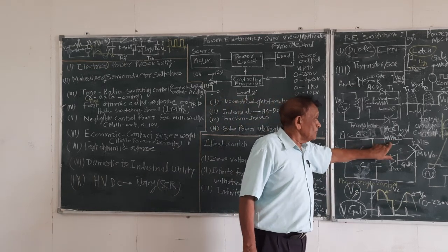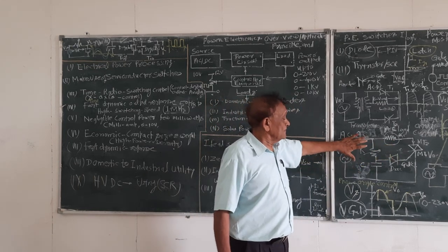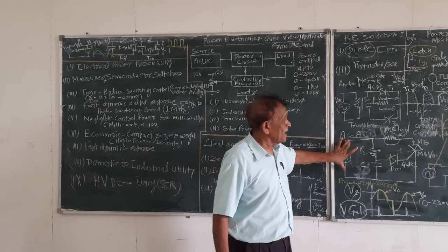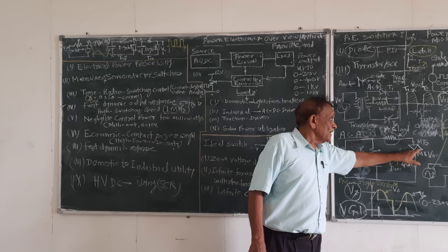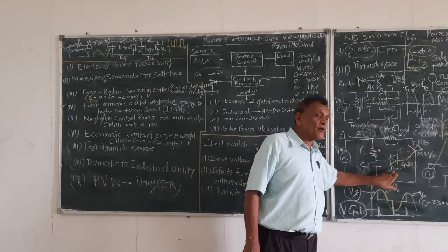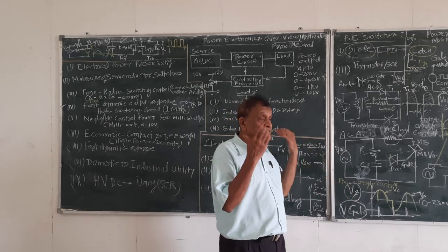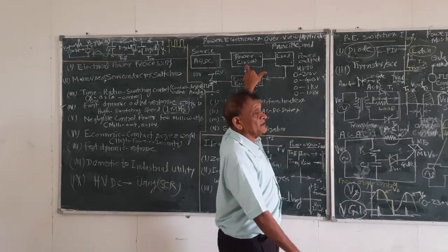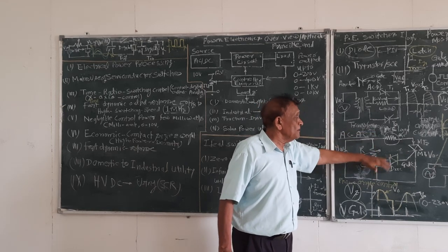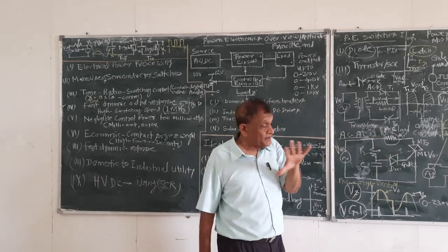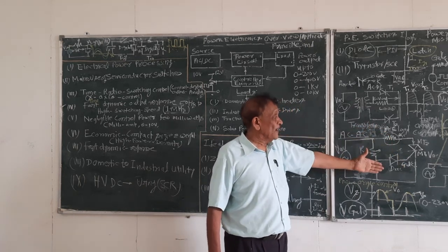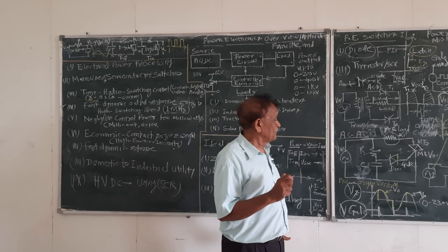So this is the fan motor which is shown by the arrow. This is the regulator shown by the arrow. This is our AC supply, and the devices in the regulator are triac and diode. So these parts are the power electronic part. They are inside this block, that is the power circuit, and this forms the control circuit. This is a very simple and low cost circuit, and it is able to control the power of the fans which can run at variable speeds.